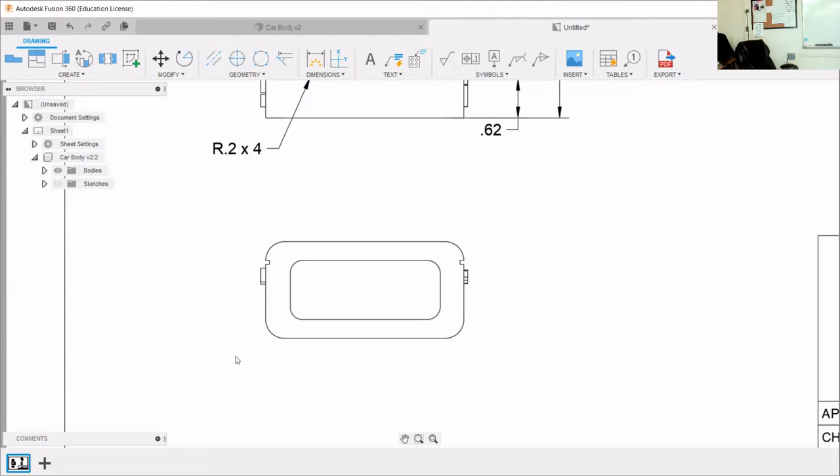We're going to do a section view that'll cut through all 3 at the same time. That's what the original document had. And I'm going to show you how to do that. So once we're done with these, we're actually going to replace that side view with a section view. But the idea is you wouldn't know that you need that until you have dimensioned all these things, and then you don't have hole depth.